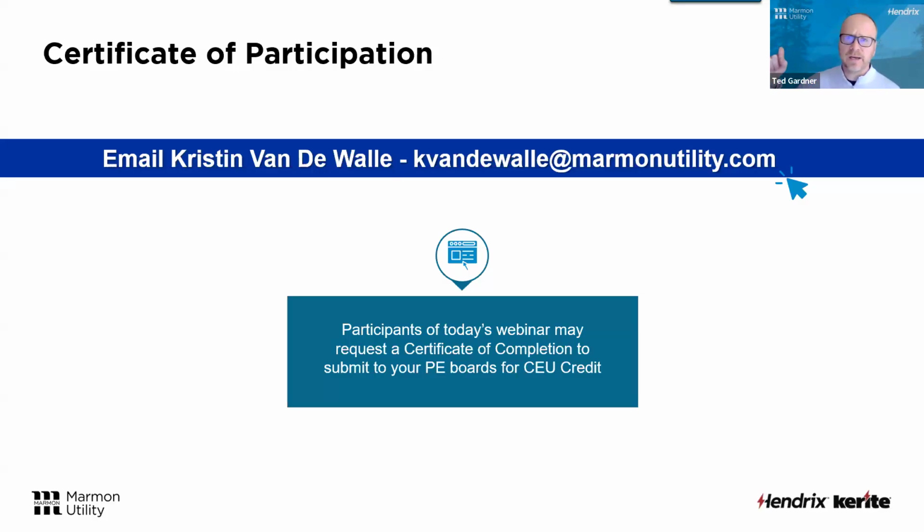That's a pretty small area because you're not really worried about damaging the ACSR. But when you've got covered conductor, you want as wide a contact area as you can so it spreads out those forces. I've even seen guys take a preform grip that's sized for that cable and loop it around a few times, and you get maybe a foot or two of contact and then you can tension it with that.